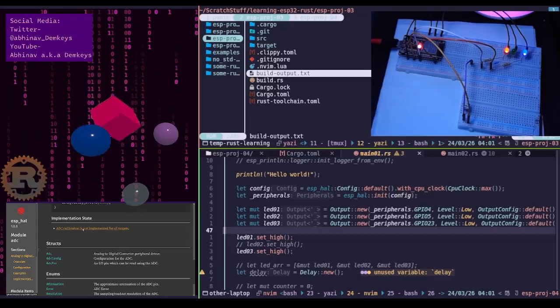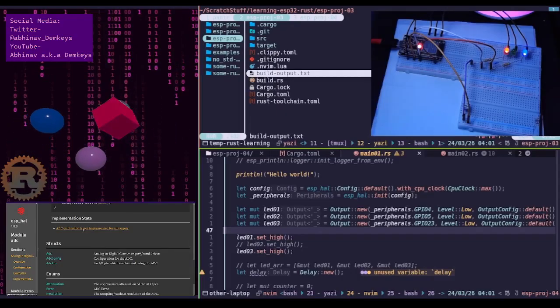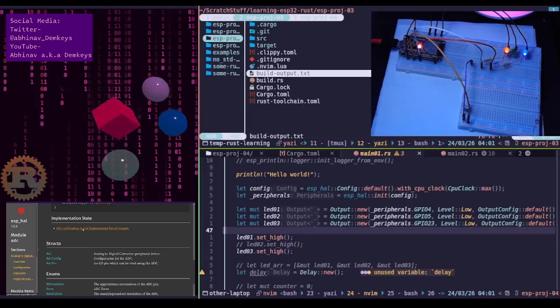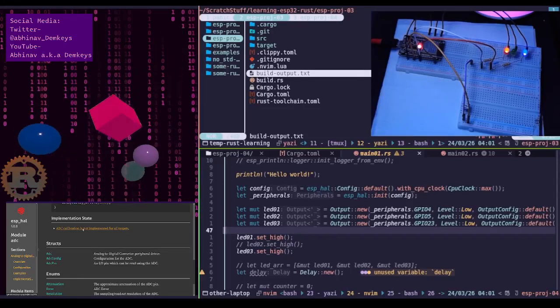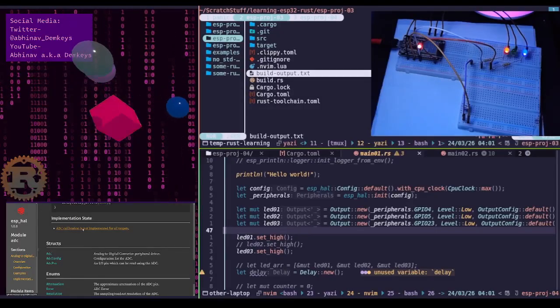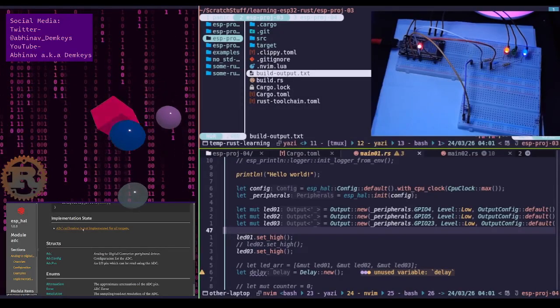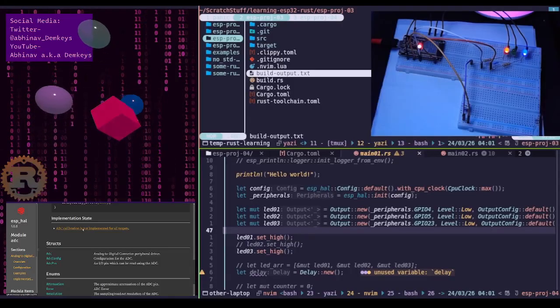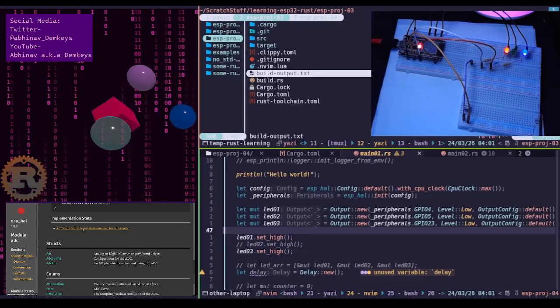Note, most ESP32 chips have ADC calibration values burnt into their eFuse memory at the factory. When the HAL says it's not implemented, it just means the software hasn't been written yet to grab those specific eFuse bits and apply the math to your ADC read results automatically.